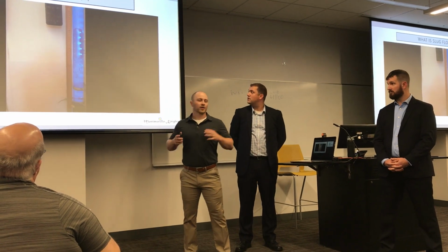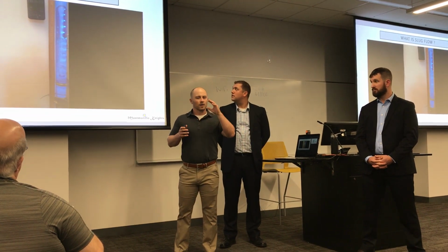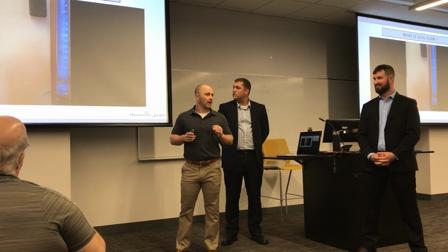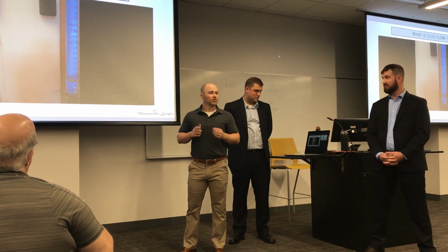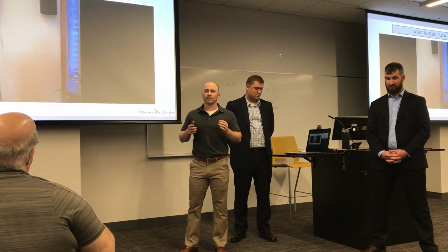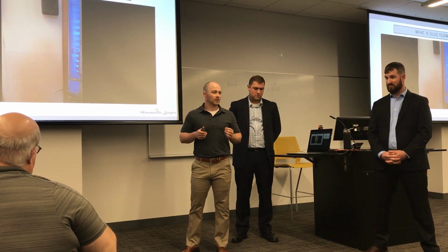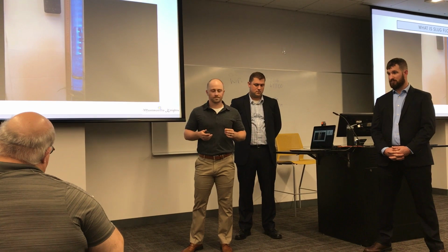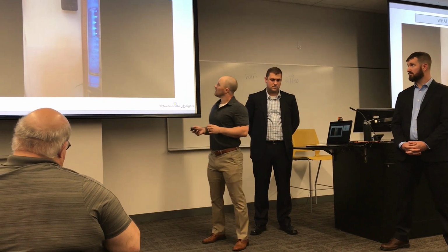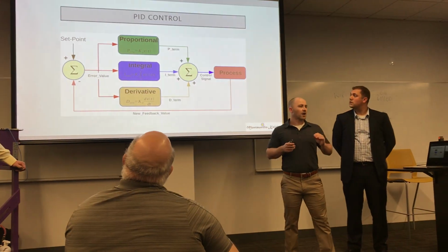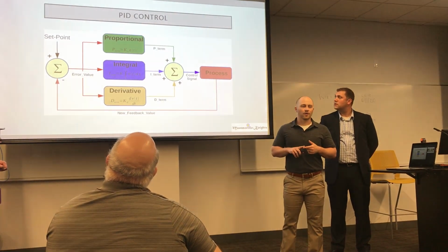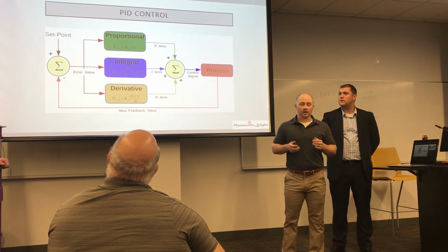A common method to combat this is the adjustment of a production valve, aka a choke valve. By closing it partially, you introduce back pressure to the system, and this back pressure reduces the velocity of these slugs, thus reducing the damage they cause. What's needed is a control method that can make these valve adjustments autonomously. Therefore, you can mitigate slug flow as well as increase production.